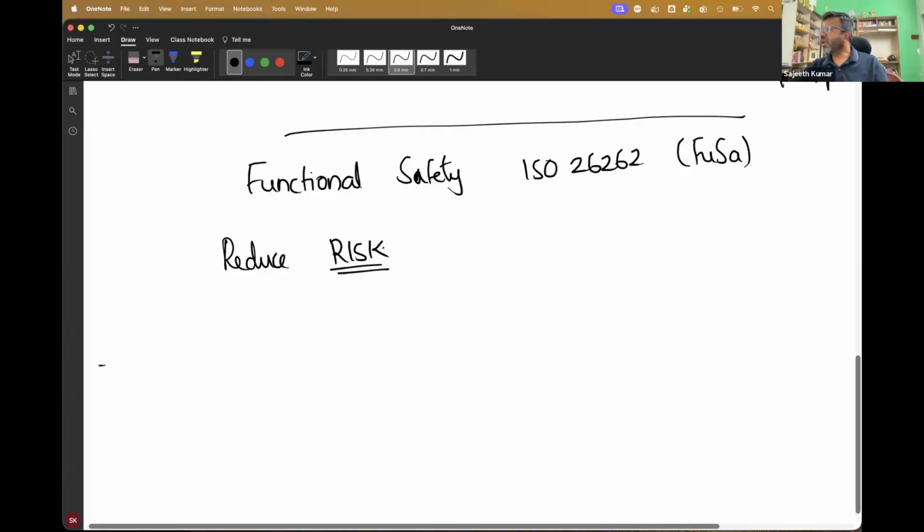LFP life cycles is more or less somewhere about 1,500 to 2,000 cycles. But the life cycle depends on the C rate at which you charge and discharge, right? And I think you will probably have to go with a standard testing agency to do it, because there's a lot of marketing gimmick that happens around life cycle. So we need to be aware of that. I would say anything more than 3,000 cycles, I don't know if it can actually happen, right?